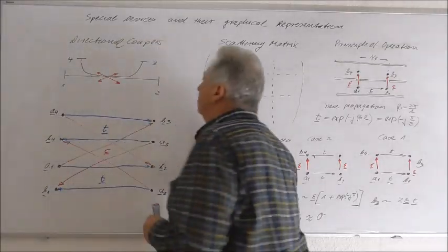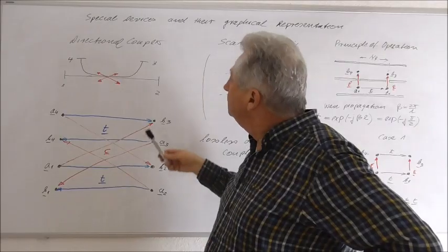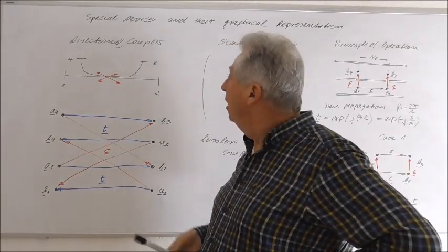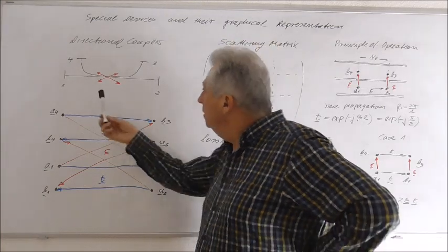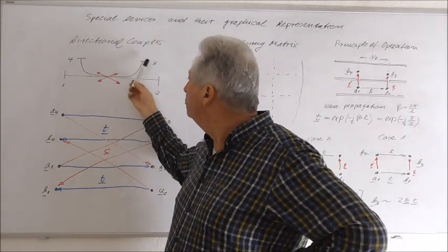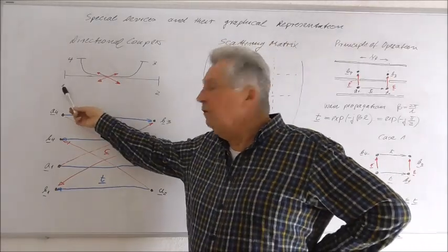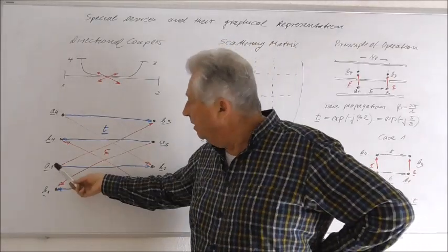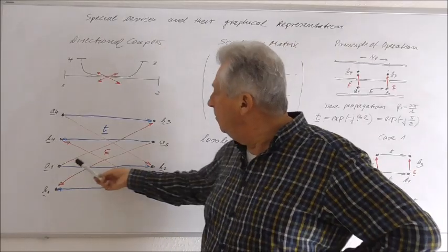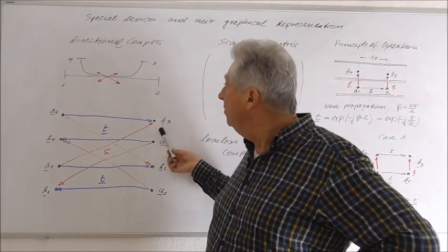And the directional coupler is a so-called 4-port, and in our case we consider here a waveguide coupler, and it's like this, that we have here port 1, port 2, port 3 and port 4. If I insert a wave into port 1, the essential wave will go through to port 2, but a part of the wave will be coupled to port 3.